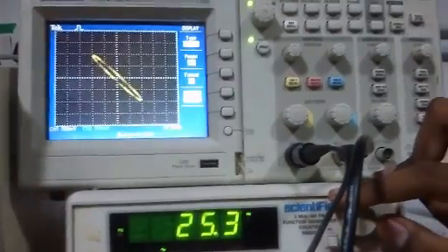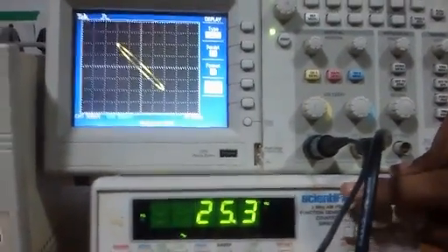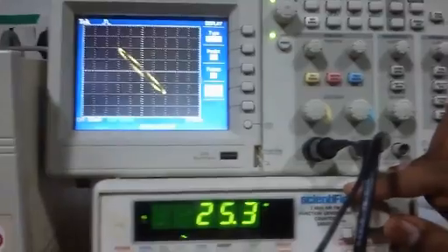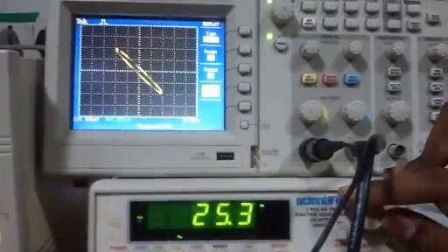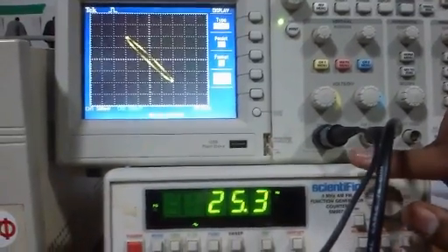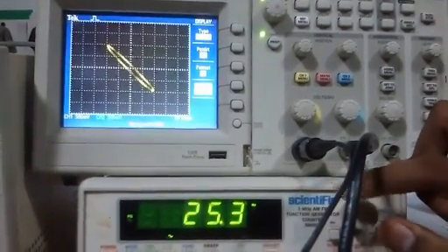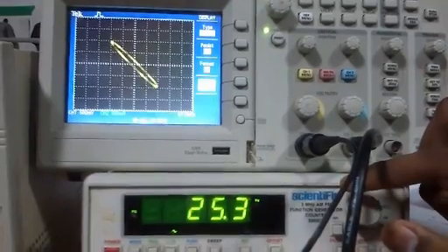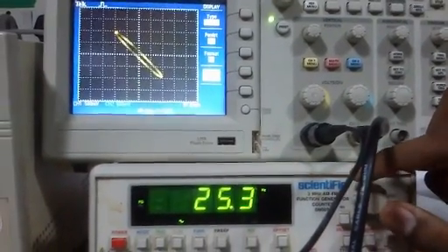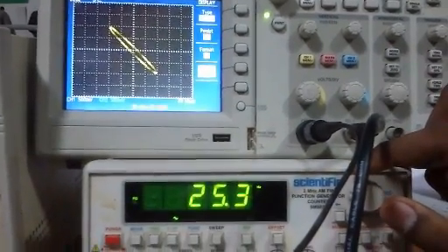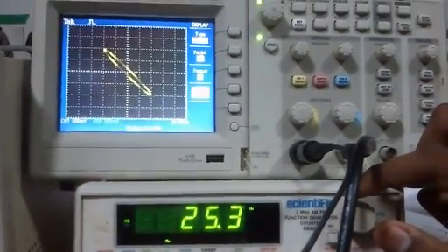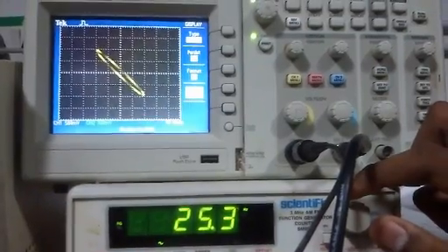So this is a digital oscilloscope, and this is an XY plot. The XY plot is essentially the plot of the amplitude of the input on the x-axis and the amplitude of the output on the y-axis. So right now the XY plot is almost a line with slope -1, which makes 135 degrees with the positive x-axis, and this is because the input and output have a phase difference of 180 degrees and have the same magnitude.